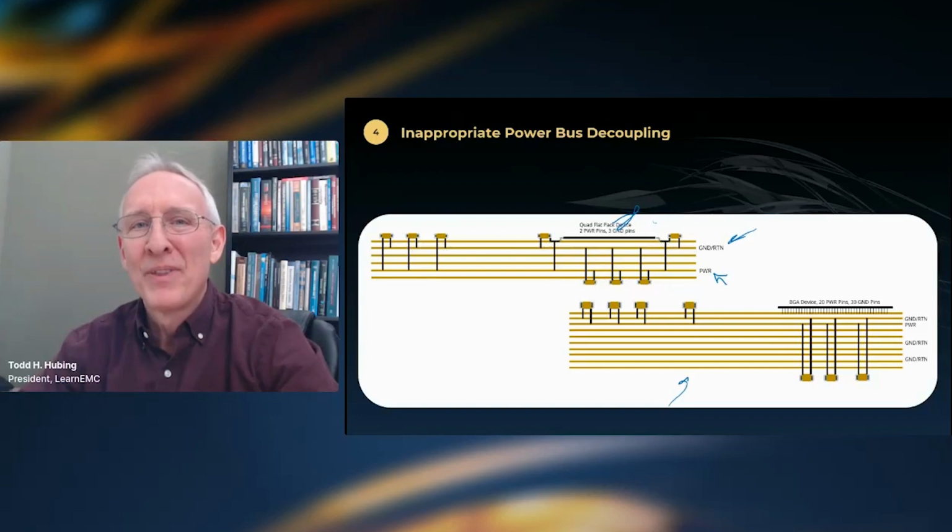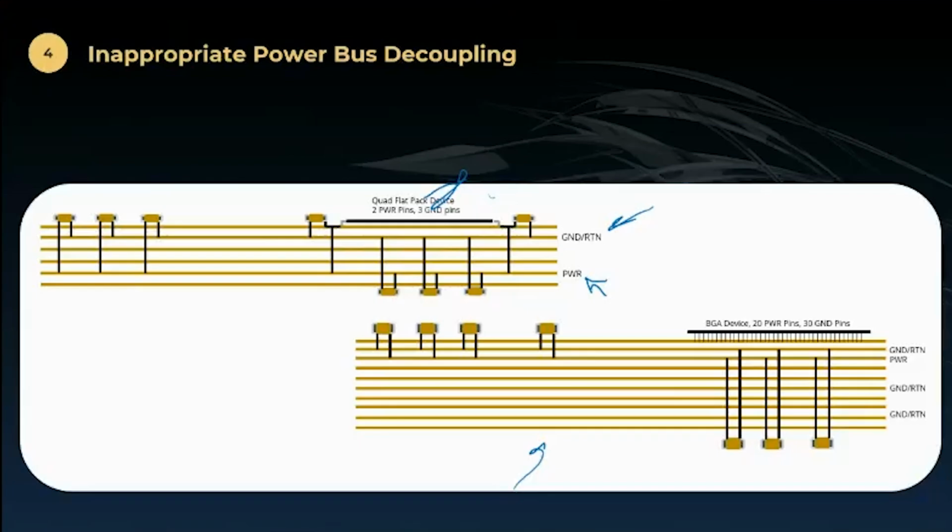But don't fall into the trap of thinking that one particular stackup is bad. It really depends on your situation, what you have, what frequencies you're working with, how much high-speed signaling you're doing on your board, and again, what types of components you're connecting to the board.